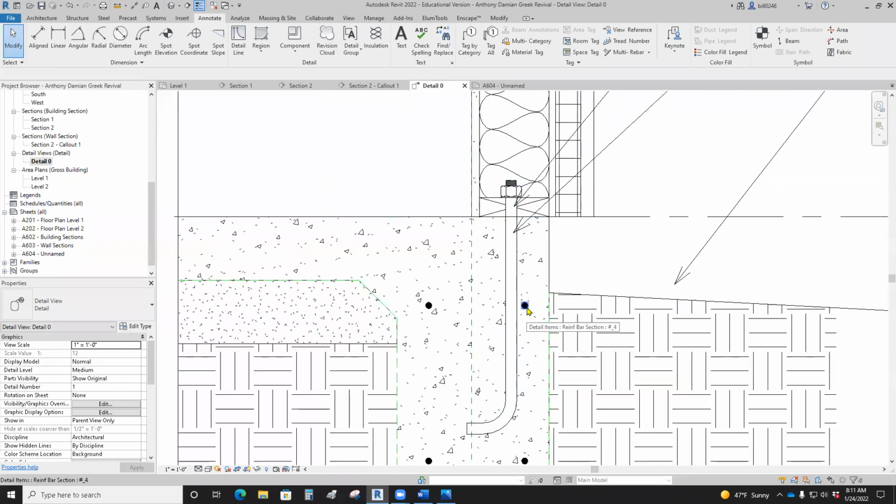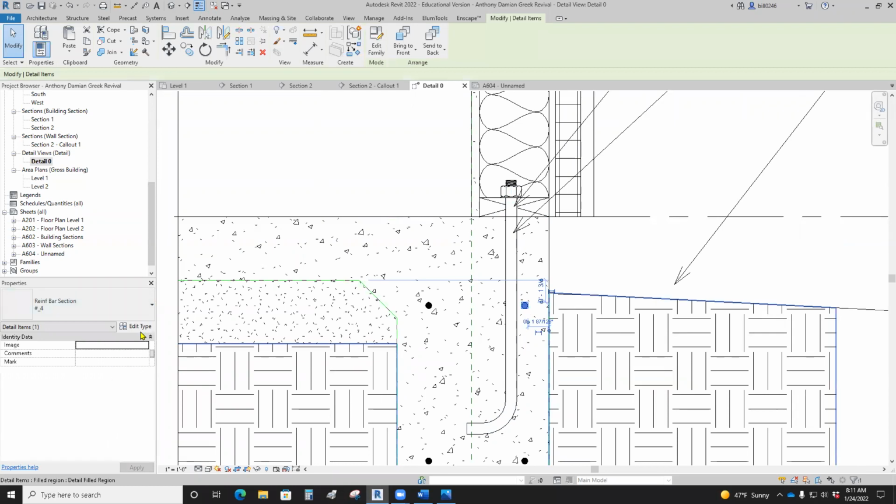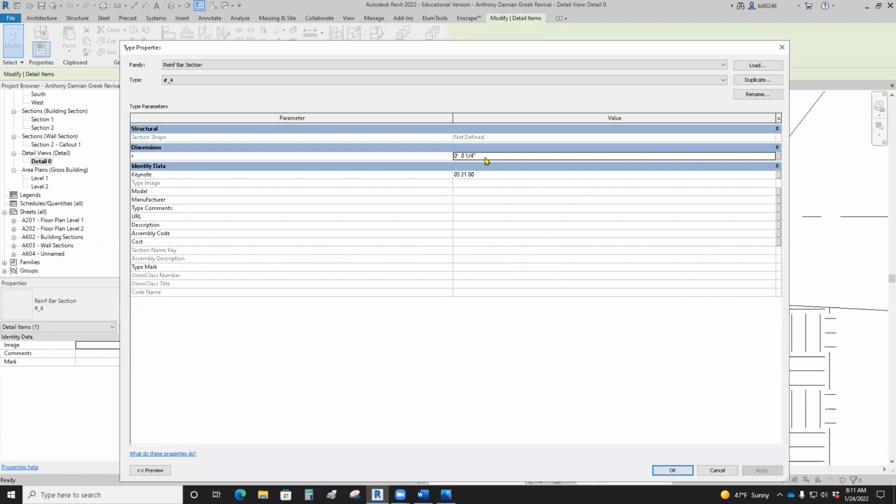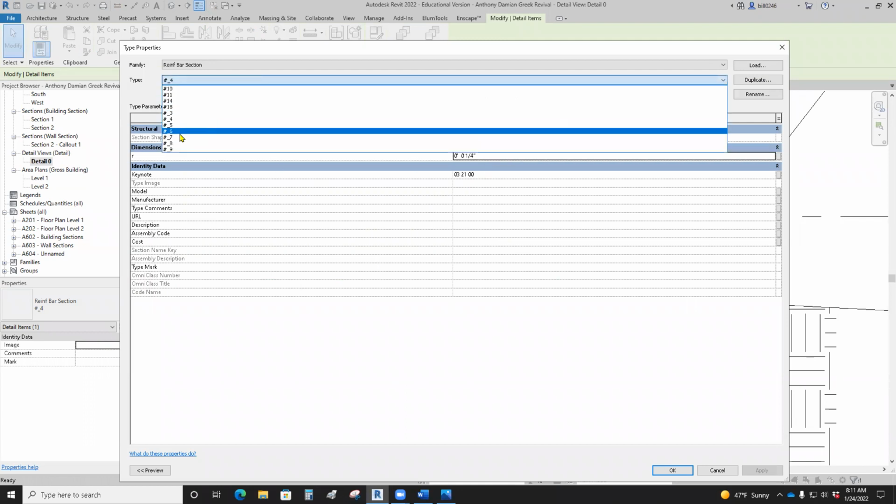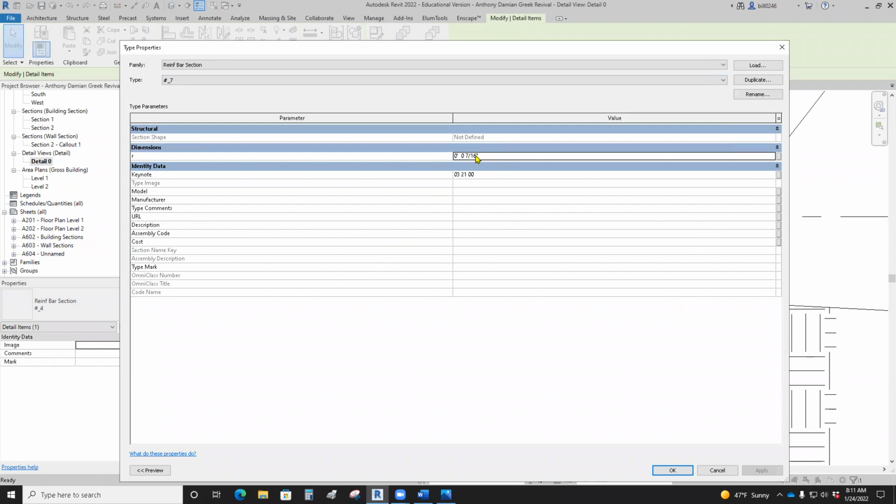By the way, on the rebar, what does that number 4 mean? Let me show you. It's how many 16ths it is. So number 4 rebar is 4/16. 4/16 is a quarter. If I was to change that to number, let's say 7, then it would be 7/16. If I was to change number 8, it would be 8/16. Does that make sense? That's a SkillsUSA question too also. All right, so number 4. So again, it all depends on the structural and all that stuff.